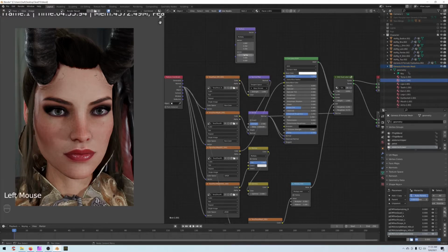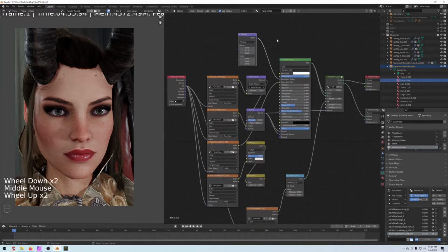And these will be our multipliers down here. I found that 0.04 works pretty good, so we'll start with that and see what that gives us. So basically this will multiply 0.04 times the red channel, the green channel, and the blue channel. It will keep the relationship between these three numbers, but it will move the distances up and down the way we need them, so we get the behavior we expect. So plug that into the subsurf, and we want the same thing.